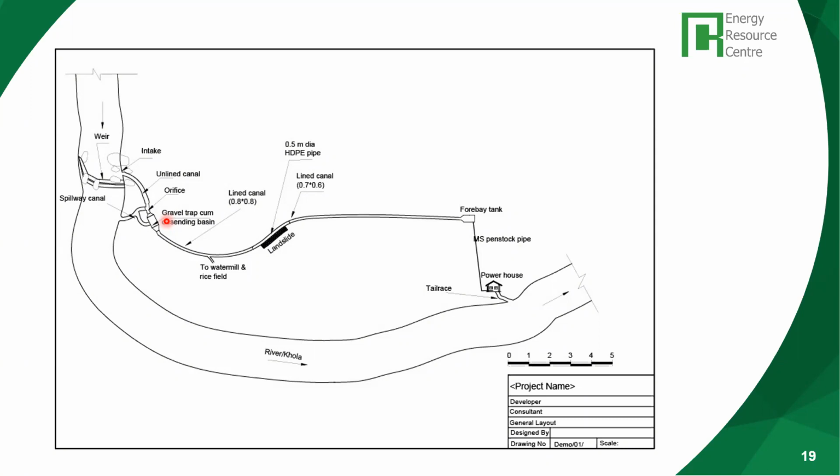most countries, they also have what they call a cadastral map. Cadastral maps are maps of individual properties, and the owners of the property are also fixed. If cadastral maps are not available, during the feasibility study level you have to walk through this canal and the structures, then list out the owners of this land. If it is public land or private land, especially, you have to get the owners and the area that is affected. That information is required.